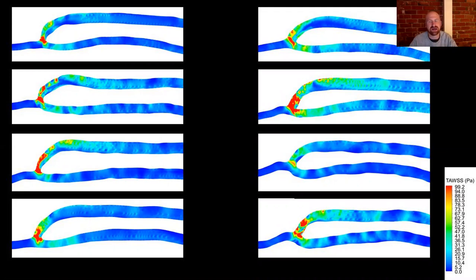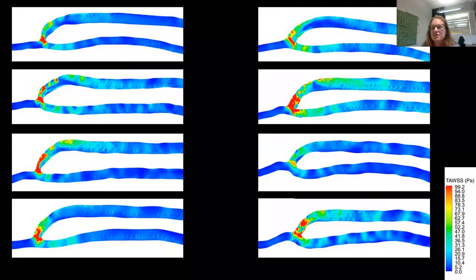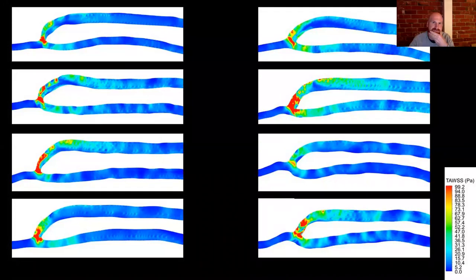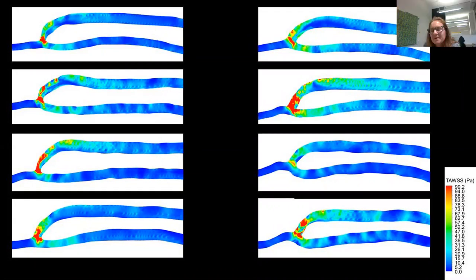Yeah, gotcha. And are you confident that when you do these CFD models of the stents that you will actually have sufficient resolution to do that? Because it's a very finely detailed structure you're trying to model there. We think so. At the moment, we're still trying to get a really good mesh around the stent struts. And I mean, it's going to be an enormous mesh once we do get it made.